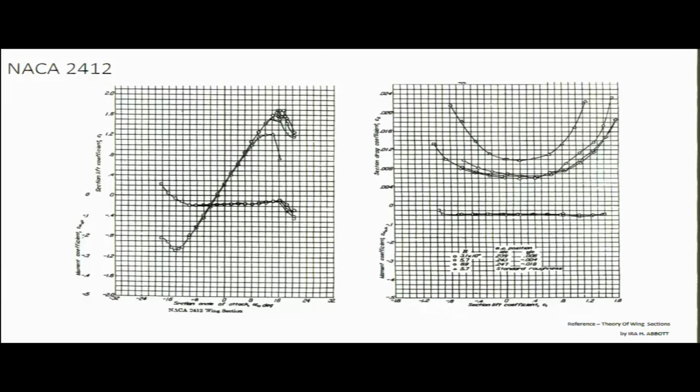Now the question is how to calculate Cl alpha, right? How is this data obtained? You can see here, this is obtained for different Reynolds numbers, which means assume that you have used the same aerofoil, but you have performed this test at different velocities inside a wind tunnel. Let us dedicate one lecture to figure out how to measure this CL, CD and CM from wind tunnel tests, or how a wind tunnel test is performed, and how these measurements were taken for aerofoil as well as wing.